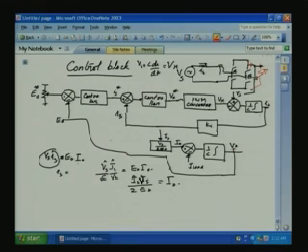So, IS we are sensing from here. Any change in the IS, through a controller, we will generate the correct VR. We will give it to the power converter, so that the power converter reference waveform, that is the modulating wave, we give to the converter such that this converter will give the correct VR. So, from this equation, Vs minus VR, integral 1 by L gives the current IS here. That IS, instantaneous value divided by K, we will feed it here. So, here if you see, this current is a sinusoidal current and this current we are controlling with this one.